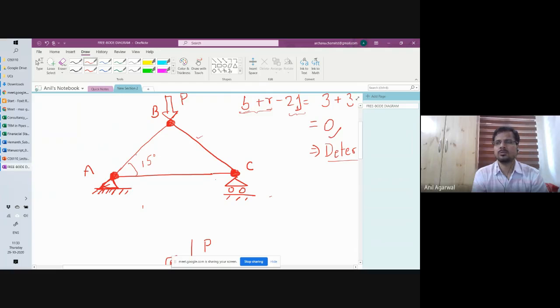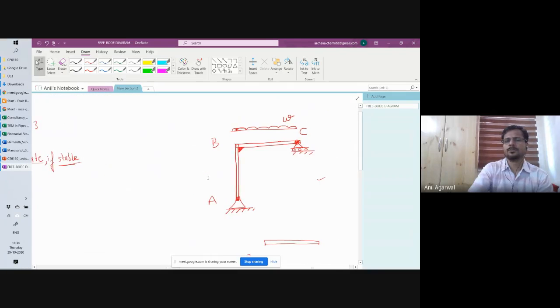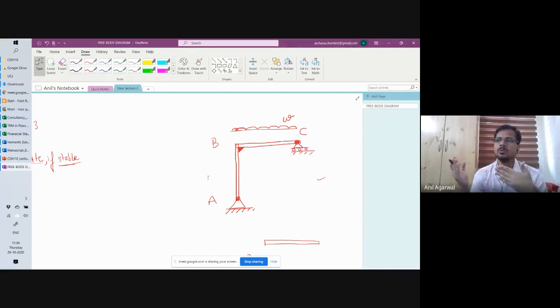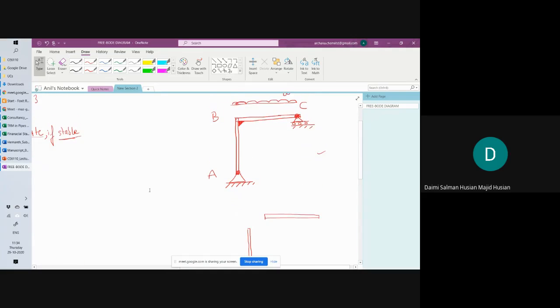So I would not recommend drawing arrows like these within the member. This is not the type of force arrows you are suggesting, right? The one that I just drew. Yes, sir. I would not recommend drawing arrows like that. That is unnecessarily confusing. Okay, sir. You should clearly mark the members, for your own good, so that you don't confuse whether a force corresponds to the joint or to the member, because the joint is applying force on the member and the member is applying force on the joint, and the two forces are in opposite directions, right? So when you put an arrow like that, you are not clearly specifying whether you are talking about the force that the member is applying on the joint or the force that the joint is applying on the member. Yes, sir. Okay.